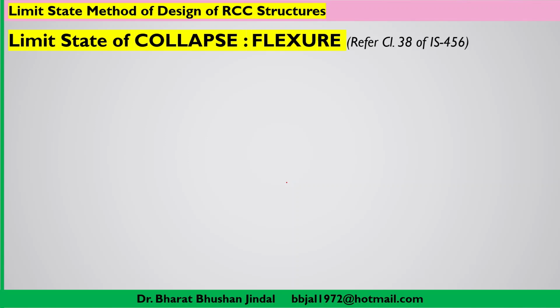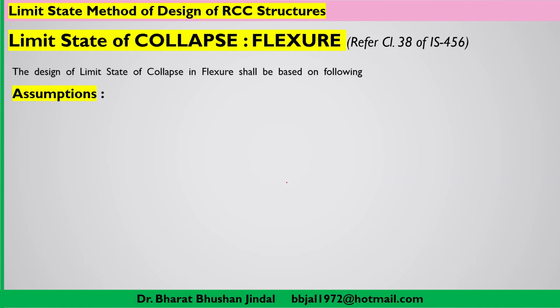So limit state of collapse in flexure, or you can say when a member is subjected to bending, we can refer to the guidelines mentioned in IS 456 in clause number 38. So the design of limit state of collapse in flexure is what we are going to discuss today. What are the various assumptions we have to keep in mind so that we can apply the limit state design methodology, that is the first type of limit state, the limit state of collapse.